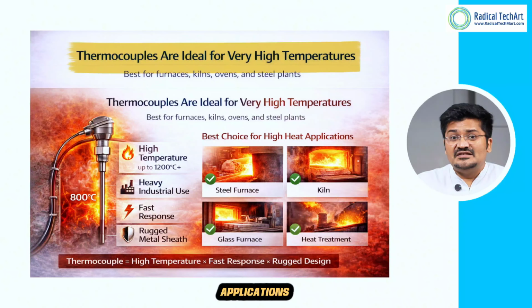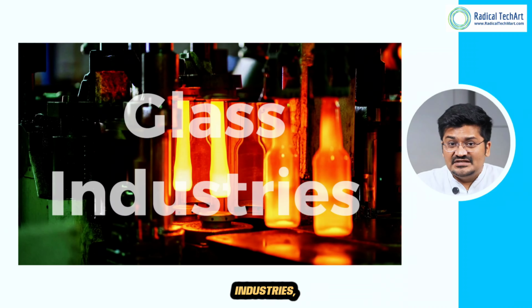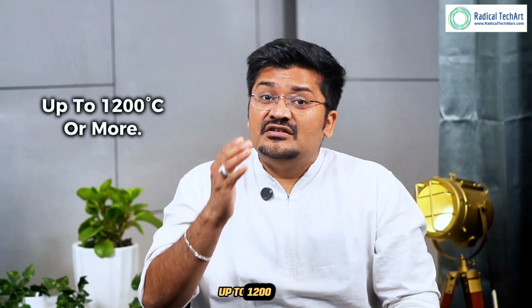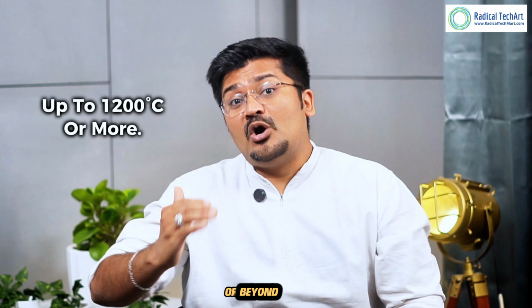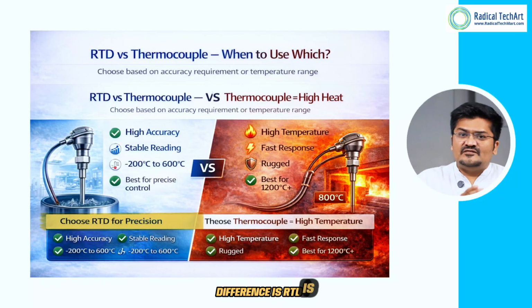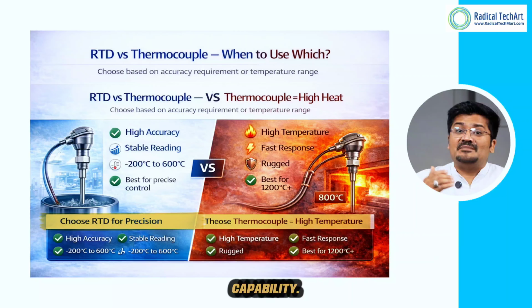Typical applications are furnaces, steel plants, glass industries, and many more. Some thermocouples can measure temperature up to 1200 degrees Celsius or even beyond. So, the main difference is RTD is for high accuracy and thermocouple is for high temperature capability.